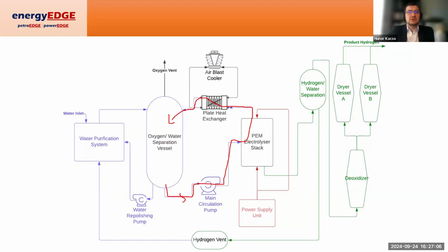One cause is fluoride release, and by the way, the rate of fluoride release is actually quite high at low current densities, contrary to common belief. In addition, you will also have impurities, especially in brand new stacks. When you fit a brand new stack, the water coming out of the stack will increase in conductivity.